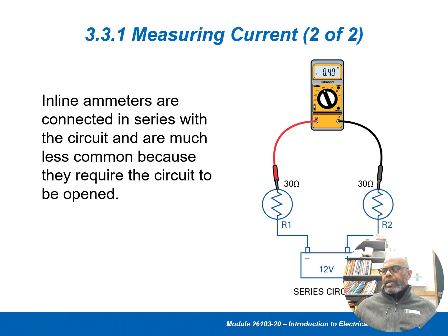Okay, this is showing an analog. Well, it's not analog, it's a digital meter, but it's using a multitester VOM to read amperage. The problem, if you read amperage this way, you can see what's happening. The problem that you have here is that we never use an ohm meter to do this, because there's a power supply, and you could damage a meter trying to read resistance when there's power applied to it. But this is an inline amp meter.